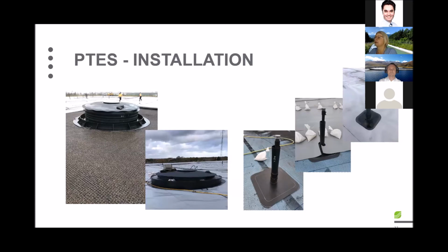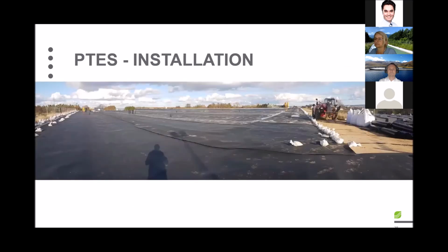This picture shows some typical elements here, the penetrations up to the lower liners. Others are only penetrating the upper liners. And there are the shafts which go down to the lower liner. Then we have the exhaust outlets, which are penetrating also the lower liner. What you can see here is that the ventilation pipe is wrapped in principle in order to have no stress due to this inner pipe, which is moving, and the floating cover is moving all the time. So we have to address that for penetrations which are going through, the stresses do not just occur in the liner connection to that element. Here's a further picture where you can see also the structures in the floating cover, which penetrate the lower liner.